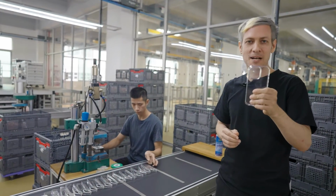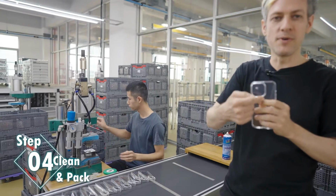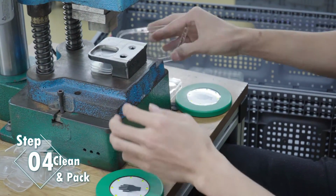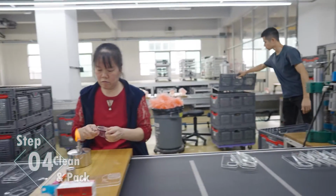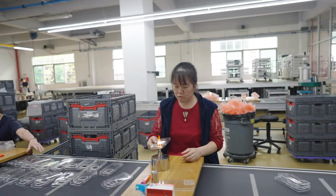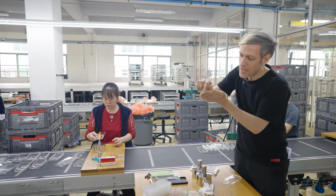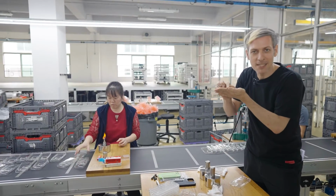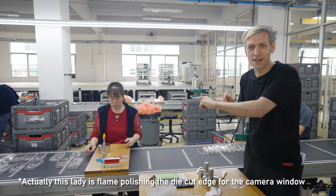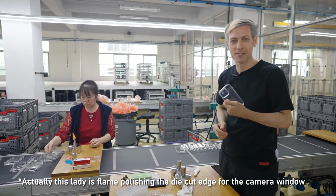There are often a few more steps to make the phone case perfect. After the parts come out of the mold, this guy here uses a die cutter to cut out this window for the camera on the phone case. And then after that, this lady flame polishes the parts, because after the parts come out of the mold, they often have something called flash. As the two parts of the mold come together, right where that line is, sometimes a little bit of plastic leaks out, and this lady is removing that little bit of plastic with the fire. And after that, the part is pretty much done and ready to be packaged.